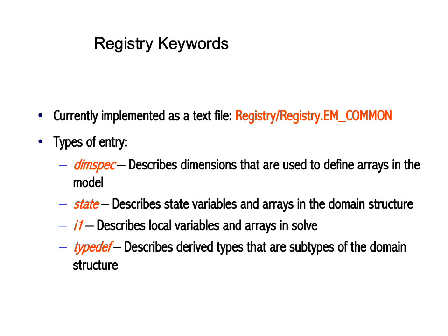The first is dim spec. This is the keyword that specifies the dimensions that are used inside of the WRF modeling system. You would think that having a I, J, and K dimension, possibly an additional dimension for the number of soil layers under the ground, would be sufficient. However, all of the single letter, uppercase and lowercase, and special characters have been used for dimensions, and now the dimensions have spread into using multiple characters.